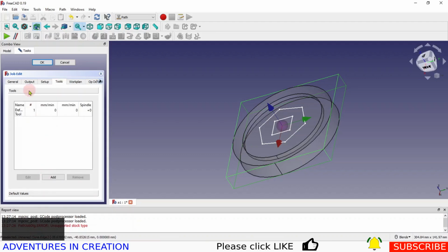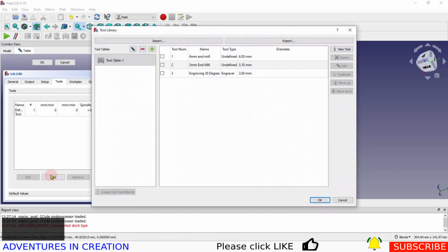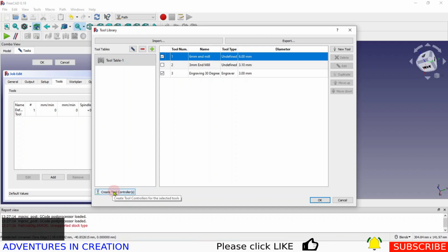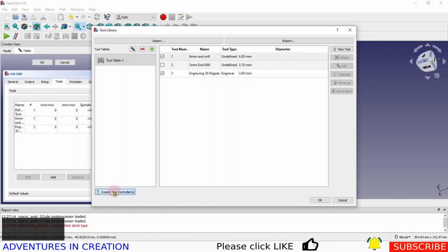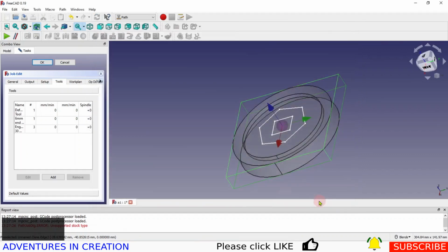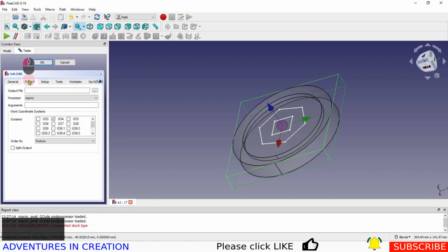And then I want to add some tools. In my library, I have an engraving bit and an end mill. I still have the old tool library in this build. There's a new one coming, but I don't have that yet. So we'll create our tool controllers, say OK. Then I'm going to click on this default tool, and I'm going to remove it just because we don't need it. So I'm just going to remove that for now.